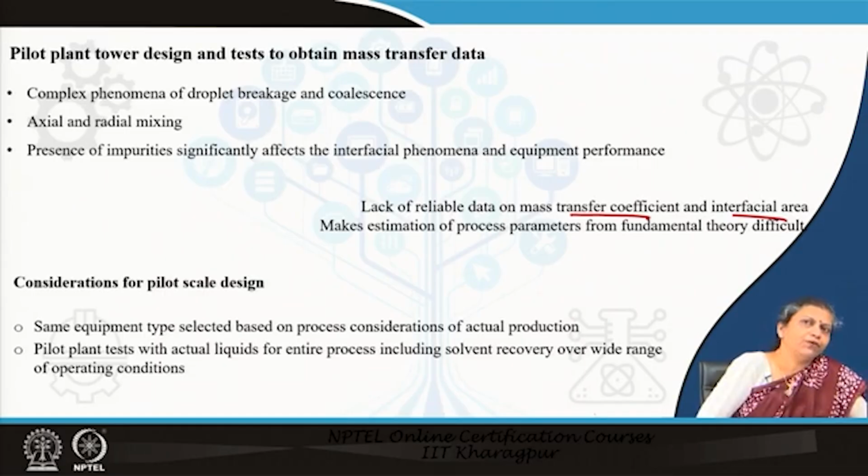Now, when we perform the tests in the pilot plant, two things are important that we should remember. First thing is we have selected the contactor earlier itself. So, therefore, the pilot plant tests have to be conducted in the same equipment type based on the process considerations of the actual production. If we plan that for this particular case we would have to go for a packed tower contactor, the pilot plant data will also be collected in the packed tower.